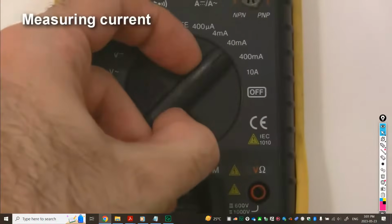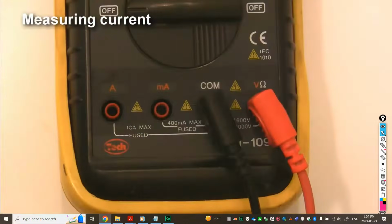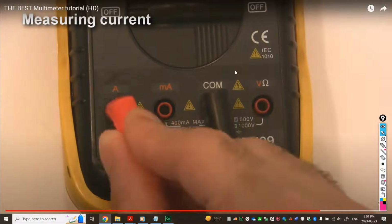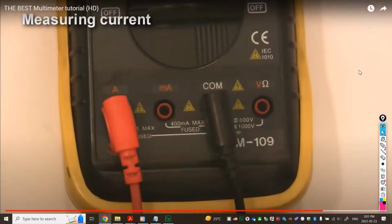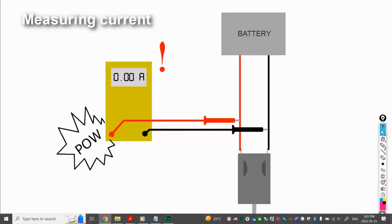Finally, let's use our multimeter to measure current. Set the dial to the amp setting. For almost all multimeters, there's going to be a separate jack just for measuring current. My multimeter has two, one for currents up to 10 amps and one for currents up to 400 milliamps. I usually start out with the amps jack, but if I need more accuracy, I can switch to the milliamps jack later. Now, measuring current is a little trickier than the rest of things.